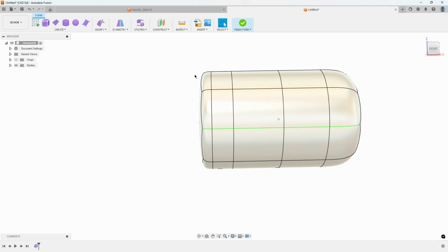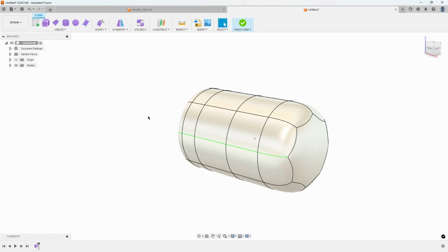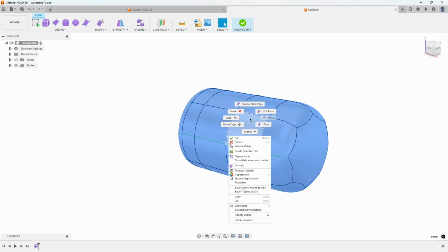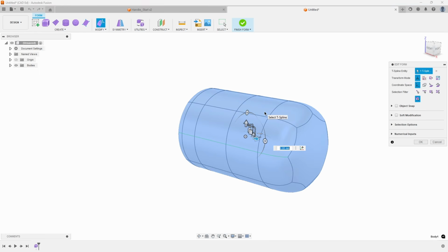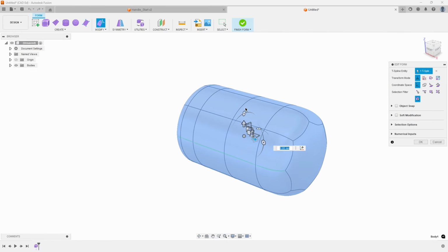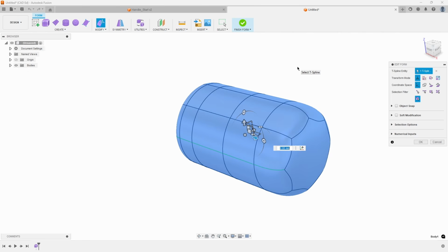Refer to Exhibit 3. Now we want to squish the cylinder down a little bit to make it less round. To do this, double-click on a face to select all of the faces of the part. Right mouse click and select Edit Form from the Marking menu. You will see a triad appear with many icons to select from. They allow you to move, rotate, and scale. You can control which transform mode you want to use by selecting it from the dialog menu.